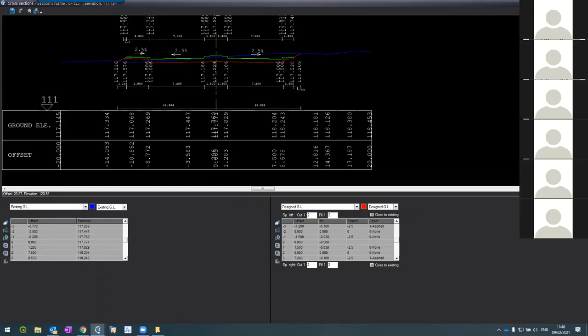In fact, as I said, I can combine the two together. You see that what happened in road number 2 is that I used extract. It means I predefined the geometry, then I create templates and apply it on the geometry. On road 1, I did the opposite. I used the cross section to create the geometry. Which method is better? There's no such thing. You decide, depends on the situation. Usually, if you have a lengthy road with not many changes, maybe it's better to run. Actually, you can start with one, change the geometry and extract back.